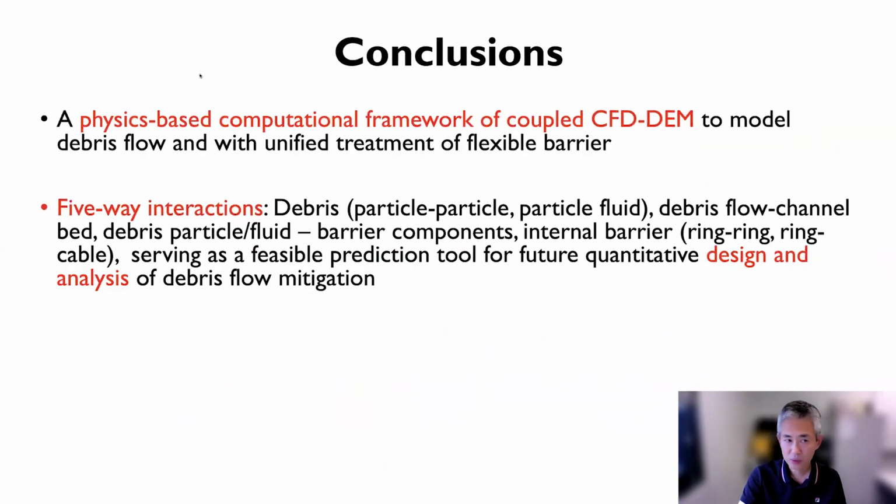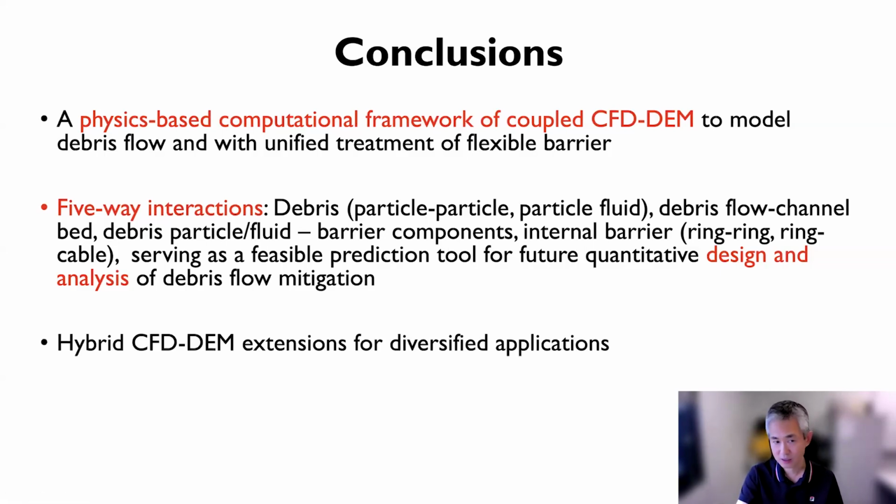So now I want to conclude this part, the whole lecture. Basically, we have developed a physics-based computational framework of CFD-DEM to model debris flow, where we can capture the interactions among the debris particles, debris flow channels, particle-fluid, and barrier components. This will serve as an analytical tool for barrier design for debris flow mitigation. And then we further extend this unresolved CFD-DEM coupling to a hybrid CFD-DEM coupling for different applications.